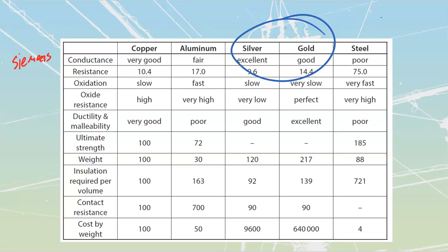A messenger cable is just going to be something that is used to support other conductors, copper or aluminum. Things like a triplex, also referred to as an NS or a neutral supported cable inside of your Canadian electrical code, are going to have a central steel conductor, and around the outside of that, it's going to have its copper or aluminum conductors that are going to be carrying the current. The steel is just supporting that.